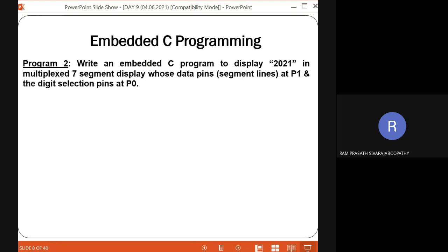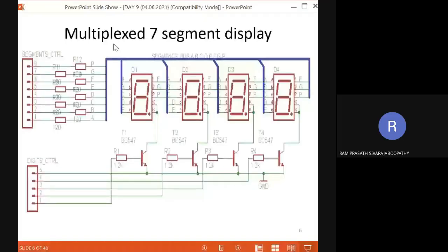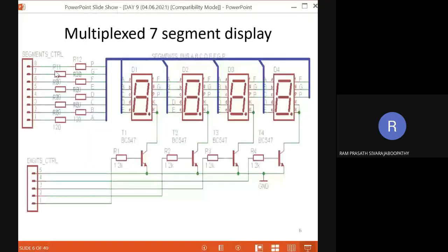That is the configuration we are using, and we call it a digit driver. Similarly, you can connect VCC to the segments using 8 transistors individually. That we call a segment driver. I hope it is clear to everyone.